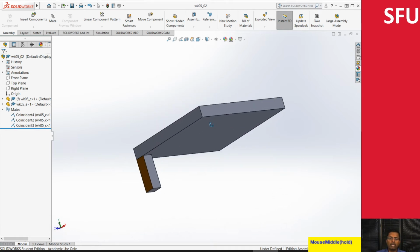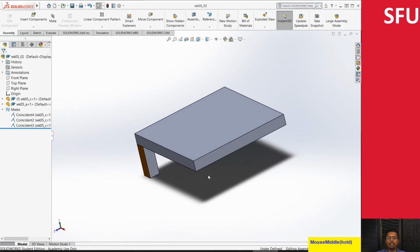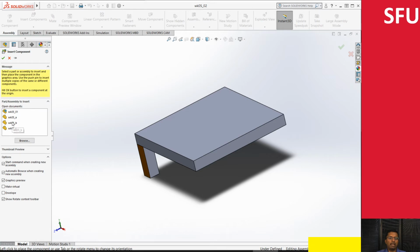What I do next is, obviously I don't want one leg for my table, right? I probably want 4 legs. If you remember, if you're making this part, you would basically make 4 legs, but all those 4 legs are going to be the same identical part. Unless there is a specific reason, you don't necessarily make completely different parts for each leg. So what I would do here is one of 2 things. I can either insert component, then click on my part A again and keep inserting it.